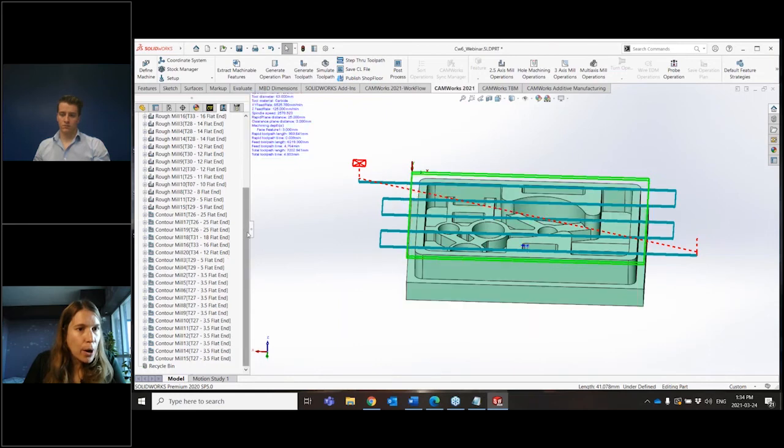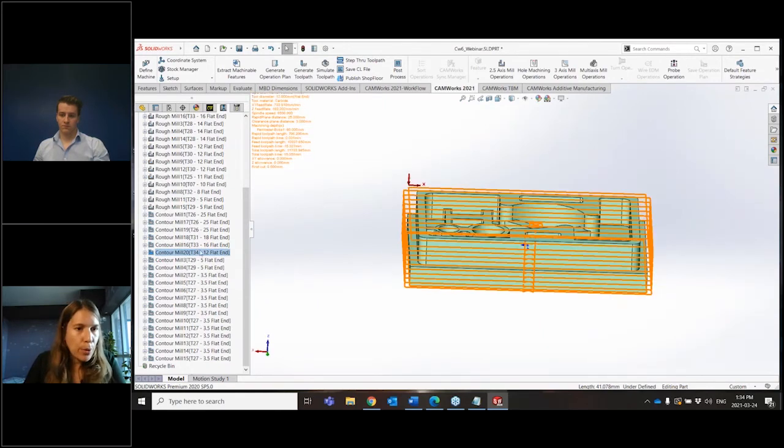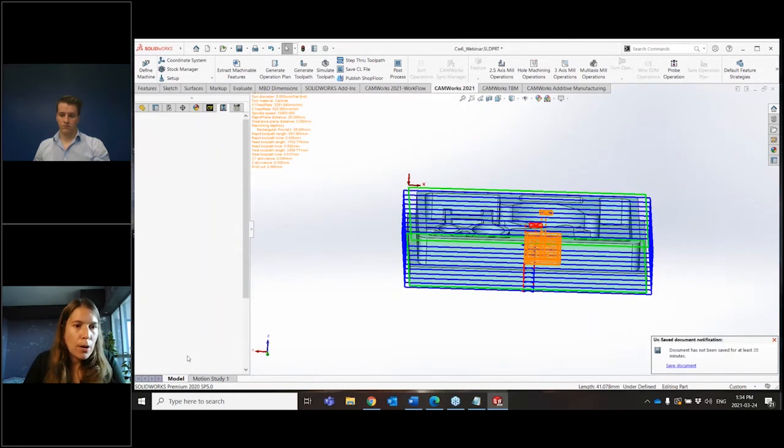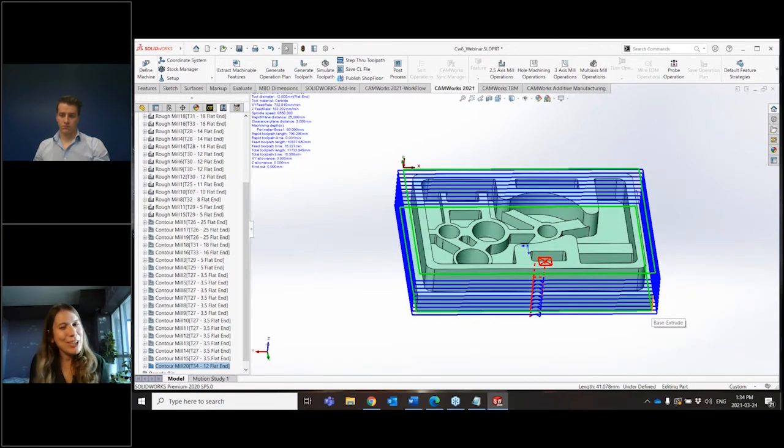We'll find our part perimeter in here. You can see that's also updated appropriately as well. I'll just drag that to the bottom because I want that to be at the end. So I hope I proved to you, Connor, that it is kind of that simple. We can click a couple buttons and program our part rather instantly.